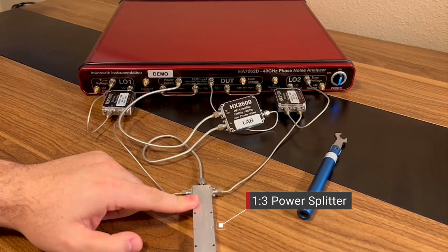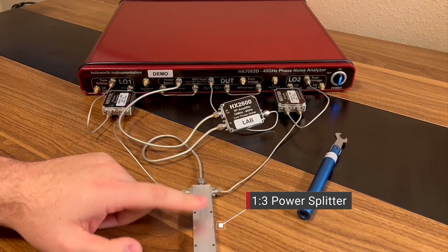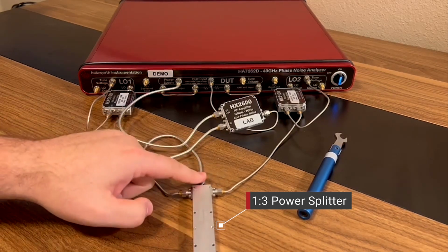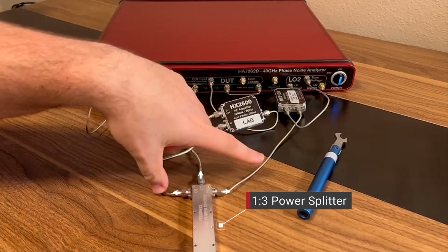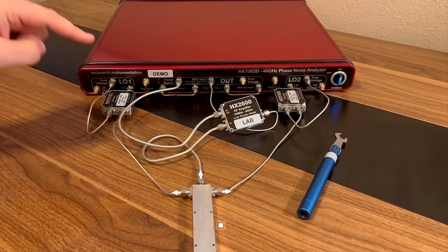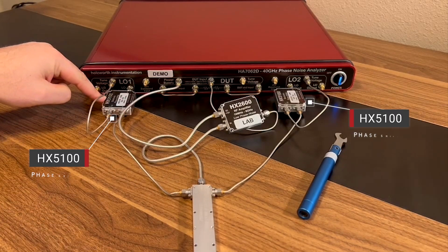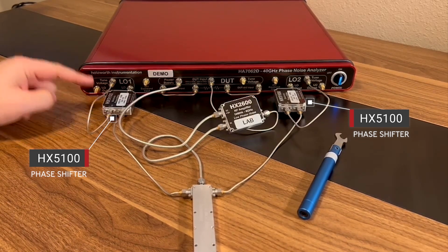Now back to the 1 to 3 power splitter. This 1 to 3 power splitter is taking a signal from a signal generator, specifically a 100 megahertz signal. It's coming in and splitting it 3 ways. One way is going to our RF amplifier, and then each one of the channels is getting its own signal. Then it's being passed through phase shifters, specifically the HX5100s, which we sell and which make additive measurements a lot easier.